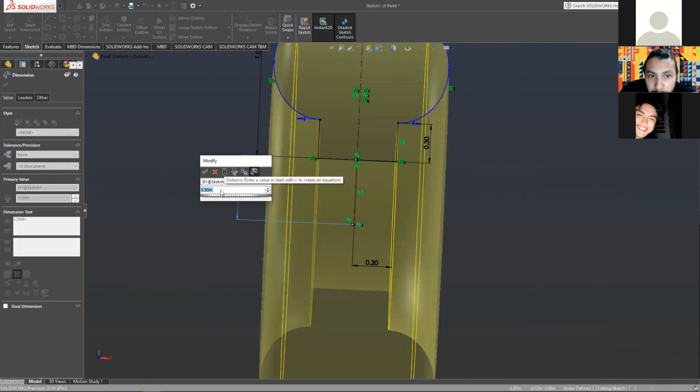As you can see, it's already anticipating that you're going to edit the sketch and change the revolution. The inner diameter of our shaft is 0.25, a 1/4 inch. SolidWorks can actually do math for you in these fields. So what's half of a 1/4 inch? It's 0.125.